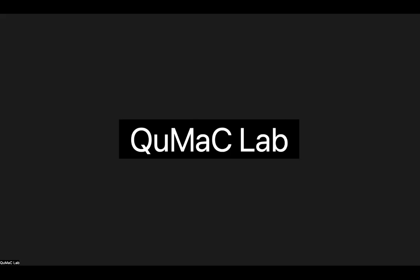There are some other aspects to IQ mixers, in that this is actually not the correct output, in the sense that when you send I equal to 0 and Q equal to 0, the output actually should be 0. But it turns out that it's not the case. There is something called an offset LO leakage, which you can model as I of t plus I offset and Q of t plus Q offset.